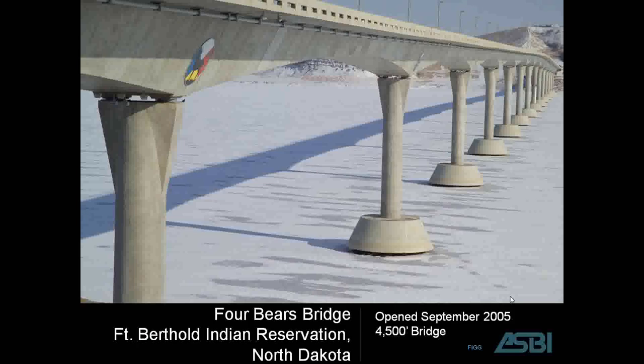I'm going to begin today with precast balanced cantilever construction, and my example today will be the Four Bears Bridge in North Dakota. This bridge was opened in 2005, and the total length is around 4,500 feet. The typical span lengths in this bridge are 316 feet, and the question may come up, why precast? Well, in this situation, there are seasonal construction requirements where precasting can occur year-round, and the erection of the structure in the field can happen during the summer months when the weather is in better shape.